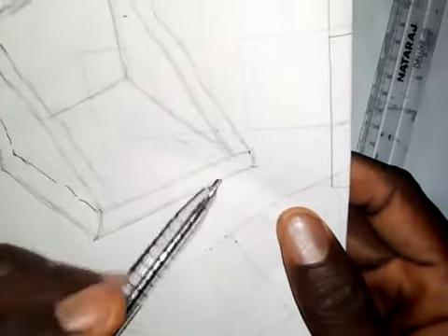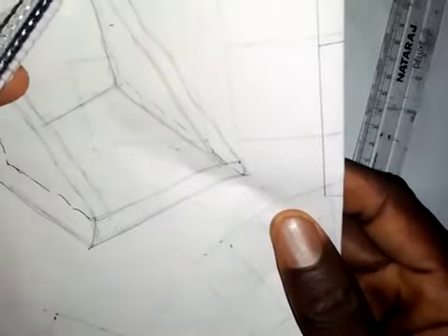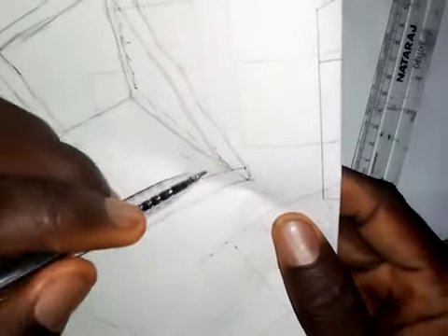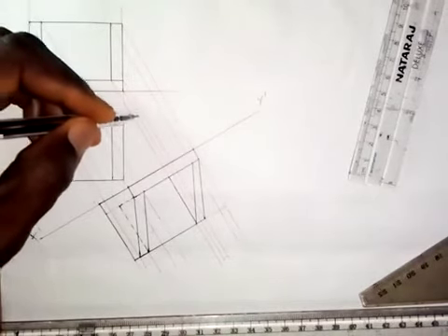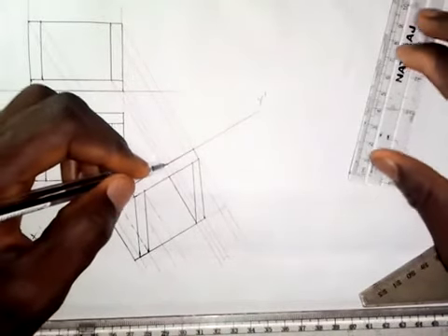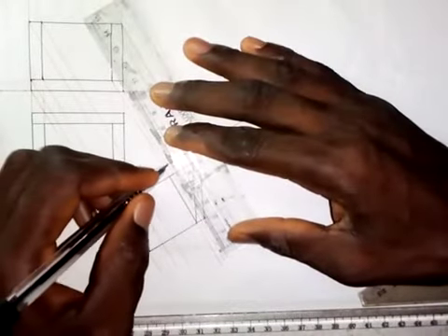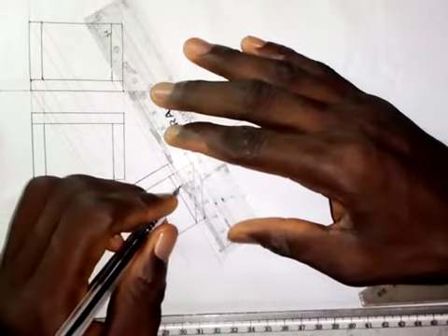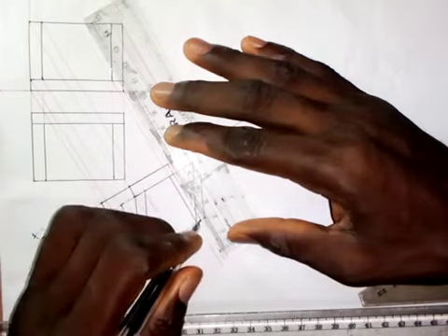Then there is one line that you can't see. That line is from here. It goes backward to this point. After we produce this down, the line is under, so we can't see it. This is its point here. So we need to draw it. I will follow this line, and it starts from the back here to the front here to this point. So I will draw it from here with a short dashes line. Okay, so I believe you followed me and this is clear to you.